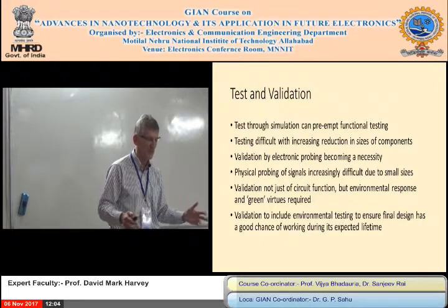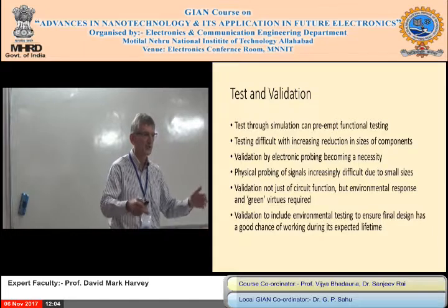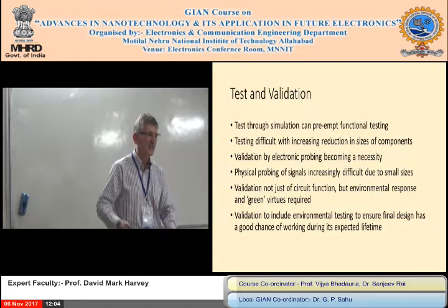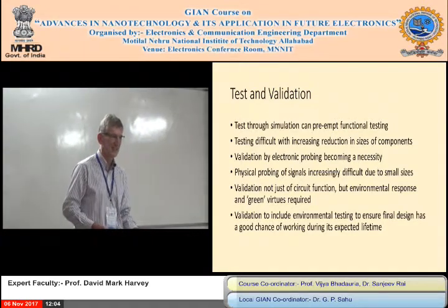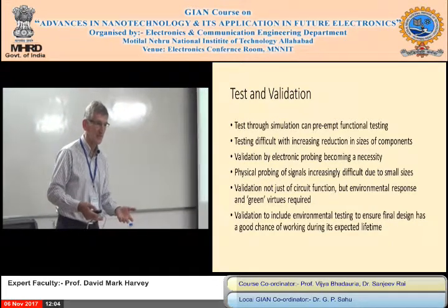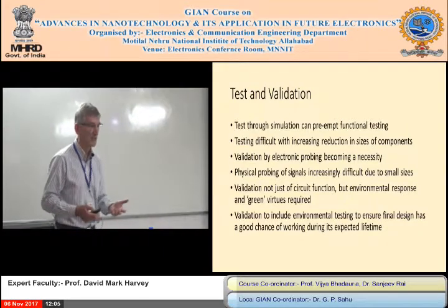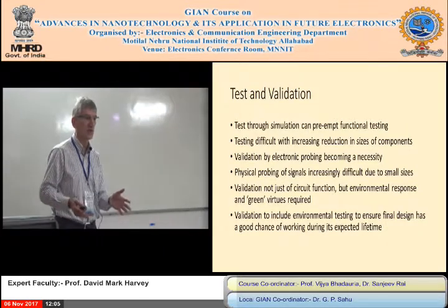And not just that, what's the vibration? Now driving on a nice smooth road in England and the roads in India, you've got different vibration. So you have to design for vibration and also humidity and maybe dust. I know in here it gets dusty and very wet. If you go to Singapore, it's like 100% humidity.